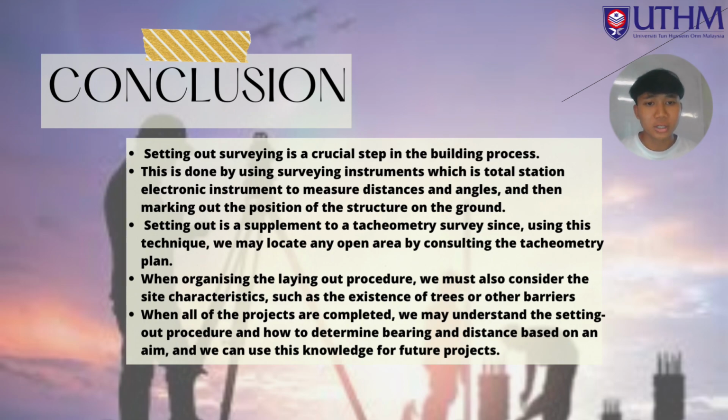In order to draw a conclusion, we discovered that setting out is crucial to civil engineering work. Setting out is a supplement to a tachymetry survey, since using this technique, we may locate any open area by consulting the tachymetry plan. When organizing the laying out procedure, we must also consider the site characteristics, such as the existence of trees or other barriers. The location of the infrastructure can be determined once the setting out is complete.